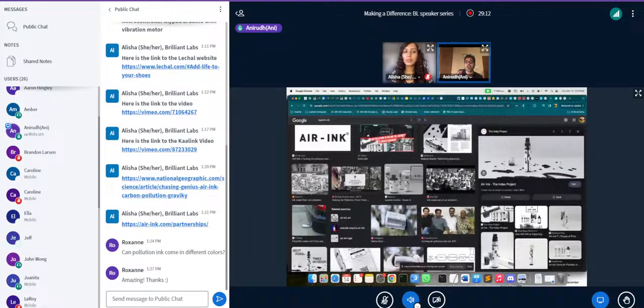You could just use a filter, like a HEPA filter, or think of a piece of foam. If you put it next to an exhaust, you can also capture carbon with it. The reason we use electrostatics is that the foam or filter or handkerchief will get clogged eventually. So you want something filterless, which will not get clogged and can keep capturing without blocking the airstream, if that makes sense.